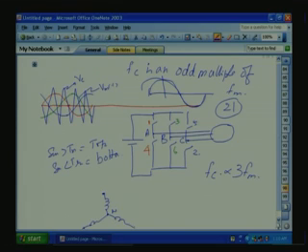So, if you use an odd multiple and 3 times the fundamental, the carrier frequency at FC, 3 FC and its sidebands, the currents in the phase will be completely suppressed.